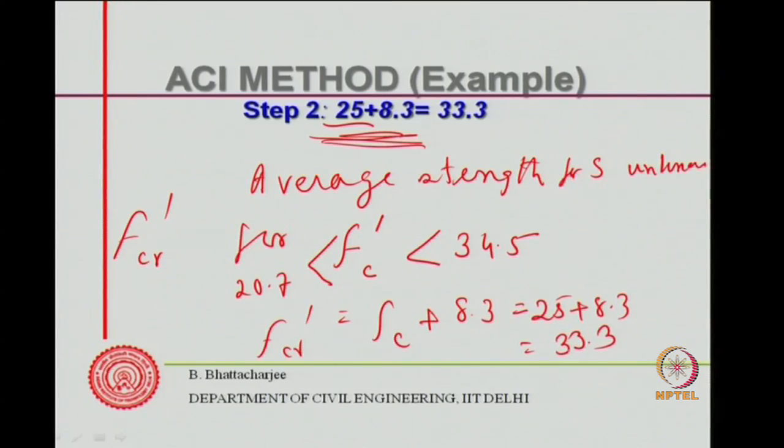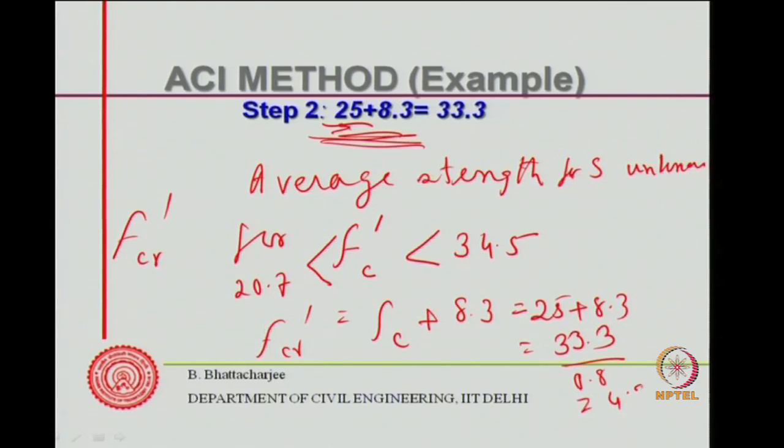And if I compare this cylinder strength, the average cylinder strength, divided by 0.8, I will get approximately 42 or 43, roughly about 43 MPa. That would be the cube strength.